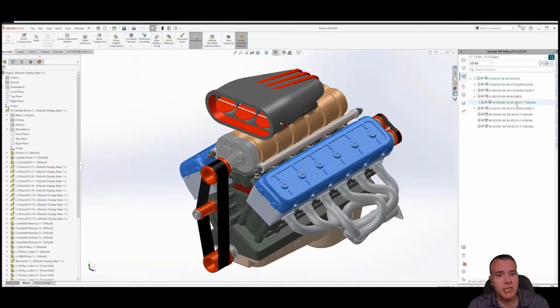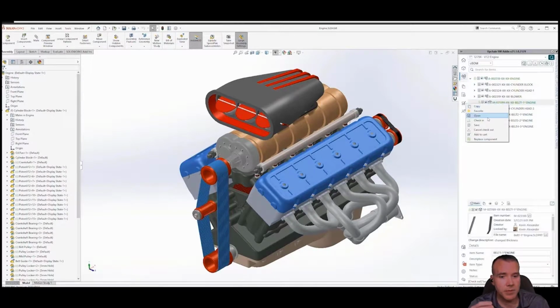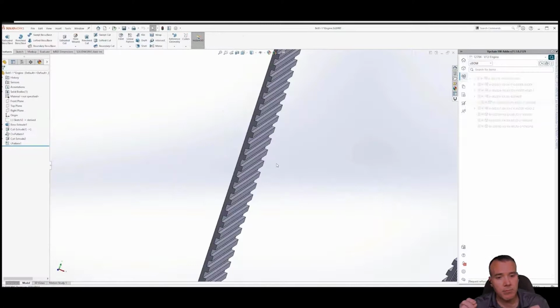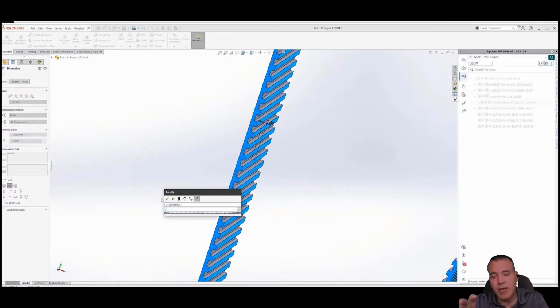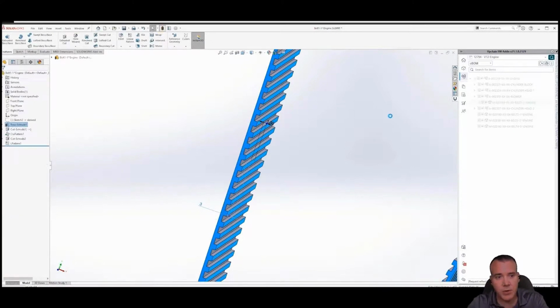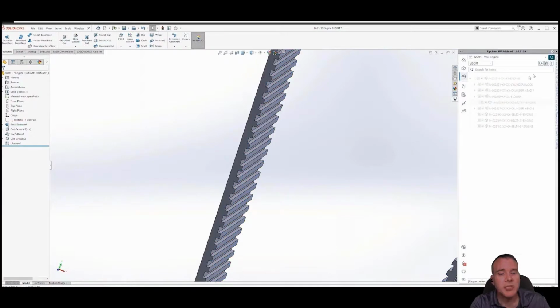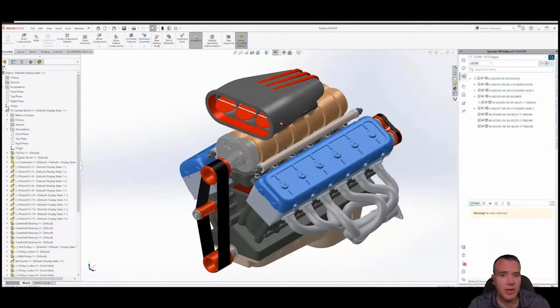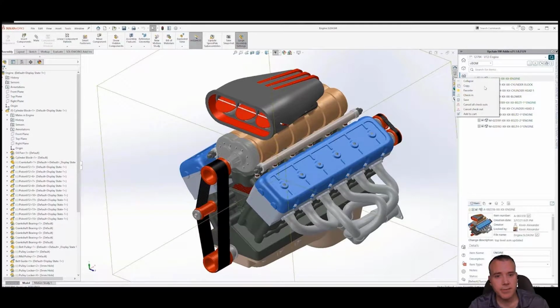So in this case, we're going to open up this belt and modify its thickness. So this is just what you would do in CAD, right? So we've now seen we have an assignment, seen what we've needed to do, and now we're in the middle of making that change, and we still have never left the CAD application. So our change is done. We can save it. We can go back to the assembly level, and we can check back in the assembly and the part that we've now modified.